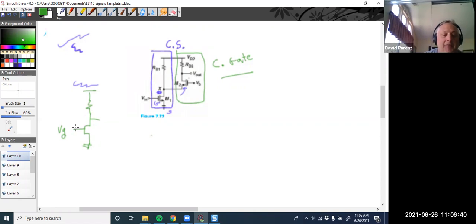And if you wanted to look at high frequency effects, you just put something in the transfer function for the op amp. But for these transistor-like circuits, there's really two steps. There's a DC analysis, and then there's an AC analysis. And the DC analysis is going to give you things like transconductance and output resistance.